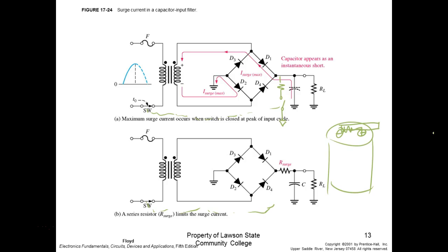So I won't have a resistor. But if I was to put a load across here, you'd see that the discharge was a lot faster. This is the problem we have. Right now I turn this thing off. I have this thing set up for up to 30 volts, right? You understand, across the two terminals. And I turn it off and that 30 volts is still there for a while. A pretty good deal of time.